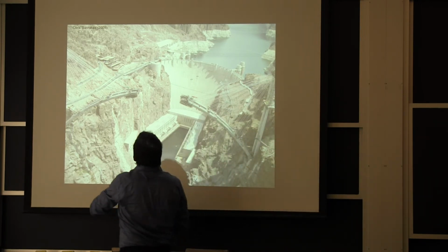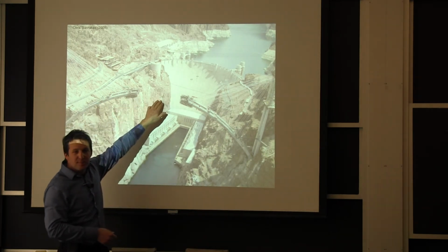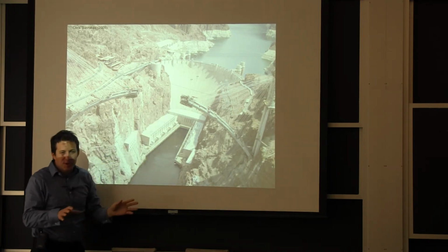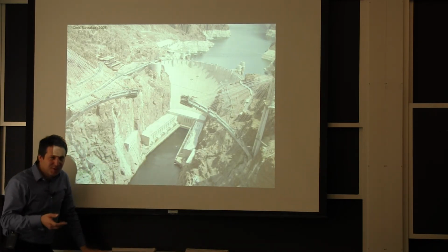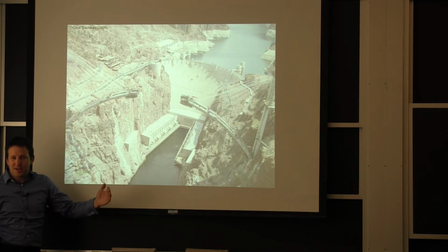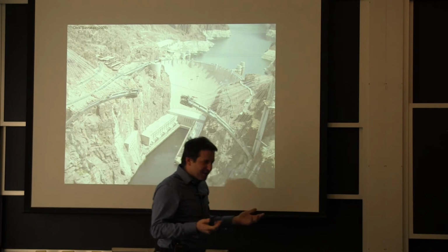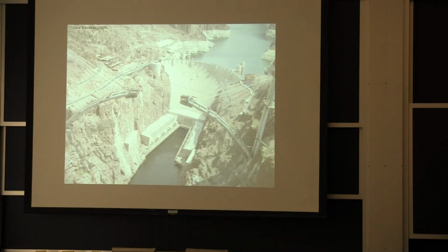We were working for the contractor here, so we had some stories about them when they reached the middle, making that segment. Everybody was worried about it. Everybody wanted to know what's going to happen because the last segment was cast in place. There was no way, coming from both ends, that you'd arrive exactly at what you wanted. So it was the very end of a very elaborate process, and yet it was the most difficult section to put together. Now it's only loaded in compression right in the middle, so it didn't need that much reinforcement, but yes, casting in place was a big adventure.